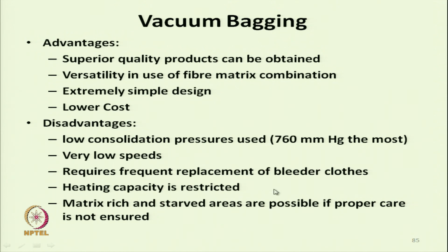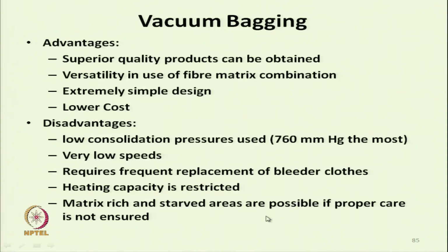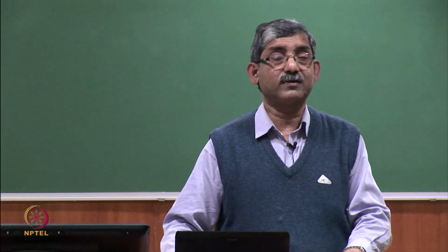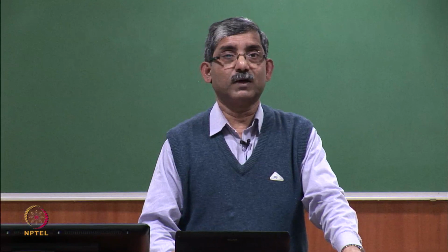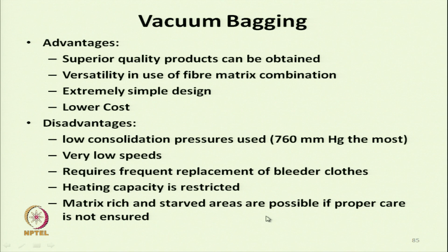Heating capacity is restricted due to different layers, the heating is not easy. Matrix rich and matrix starved areas are possible if proper care is not taken, because we are not adding any extra matrix material; it is a low pressure compression system. That is why chances of matrix rich and matrix starved areas are there. So, we must ensure proper impregnation of reinforcing material with the matrix material.